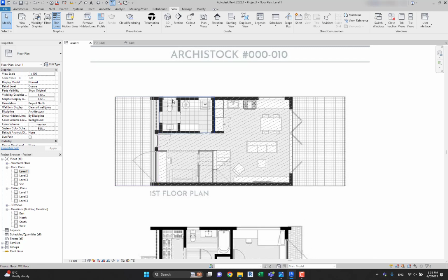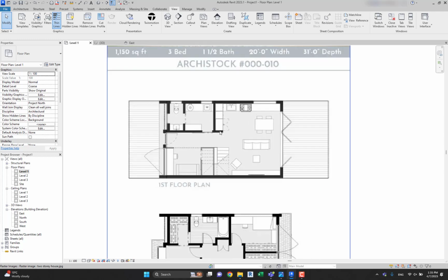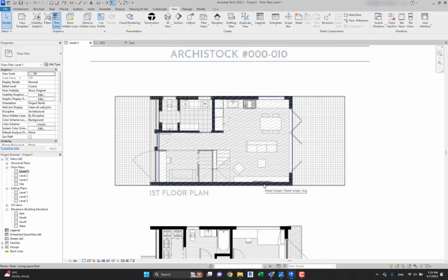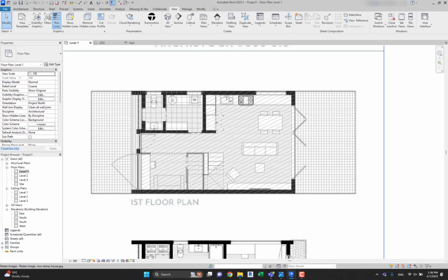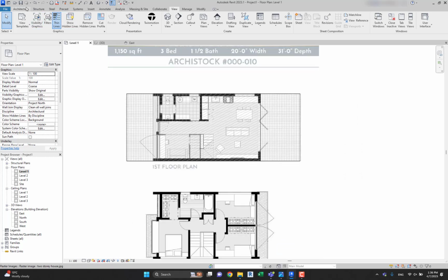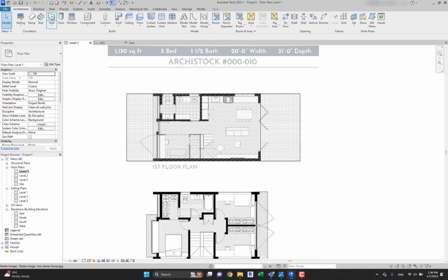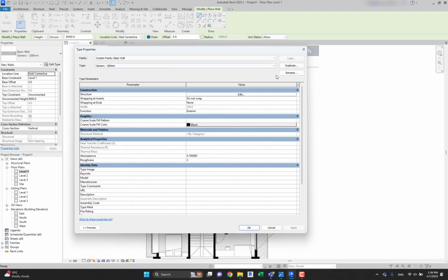Yeah, and I'm gonna create 3 different types of walls. Actually, no, it's 6 meters, because my guts of a structural engineer says that this wall should be a bearing wall as well, but it's only 6 meters, so it's gonna be just fine to create only exterior walls and interior walls, 2 different types. Okay. Let's go to Architectural tab, navigate to Walls, and let's edit the type again. Let's create Exterior.